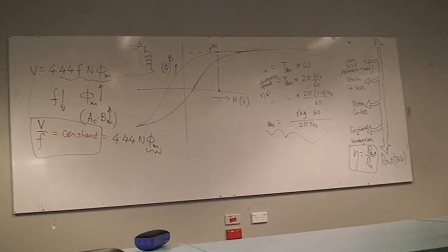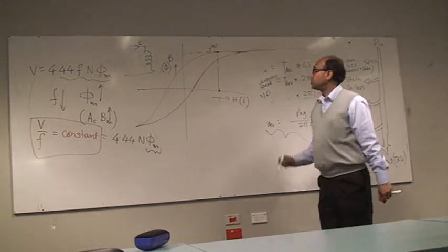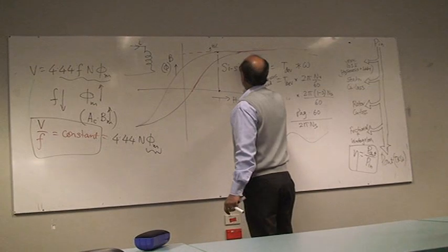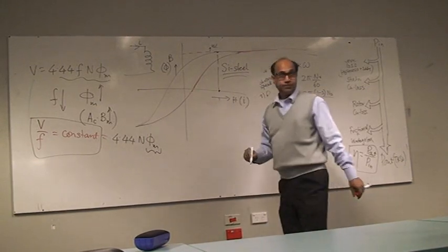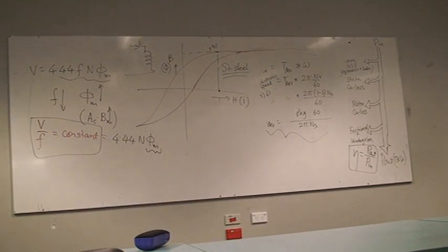Where does that limit come from? Where does the BH limit come from for a particular material? Is it related to the conductivity of the material? The BH limit comes from the BH characteristic of the material you have used. So basically this will be the material you have used for making the motor. Usually we can say it's silicon steel. If you use a superconductor or something, that has nothing to do with the hysteresis in the core material of the motor. A superconductor is for carrying current. That's a different part. You have to have material which actually produces your flux. So that's the core material. Do superconductors produce flux? A superconductor is carrying current, so you're replacing the winding, not the core.